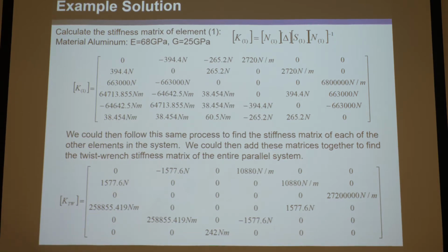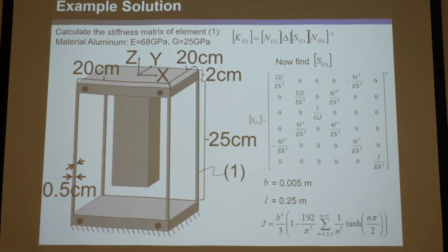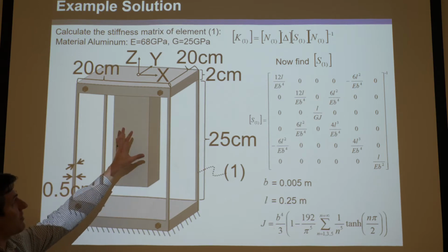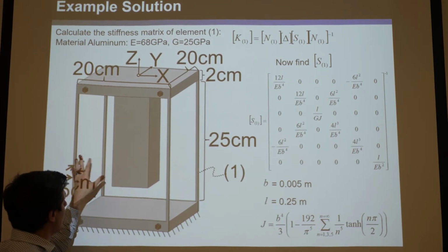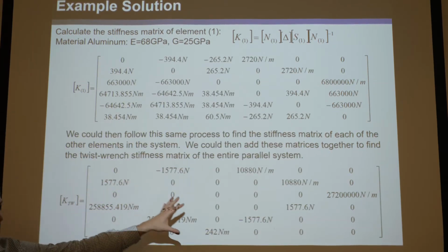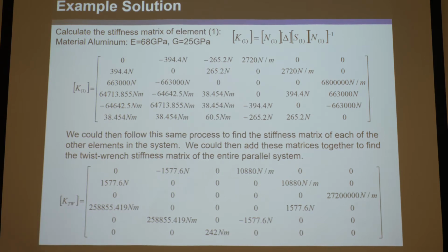And please go check me at home, do the math, let me know if you get the same matrix with the same units. Another thing you'll notice is we're assuming for this that the stages are infinitely rigid. We're not taking into account their shape, their size, or what material. This is completely independent of the stages, or the rigid bodies, and has everything to do with just the wire flexures. So the only information in the stiffness matrix pertains to the flexible elements, which makes sense. With our assumption that the rigid bodies are perfectly rigid, the flexible elements are the springs, essentially, and therefore provide the stiffness.